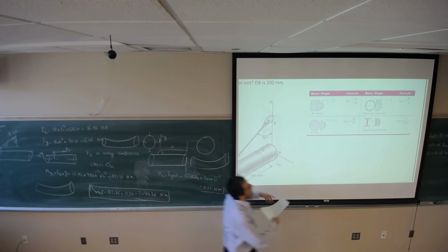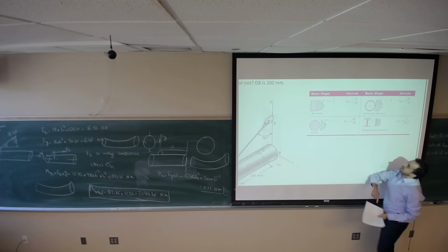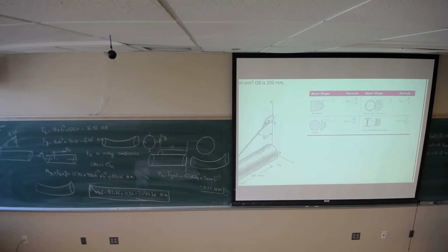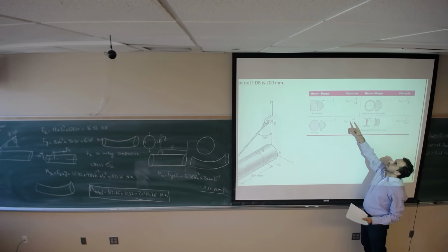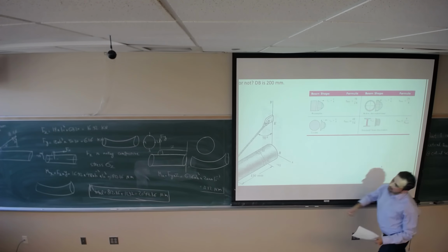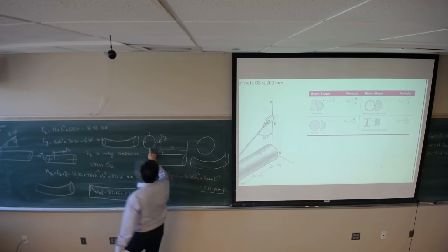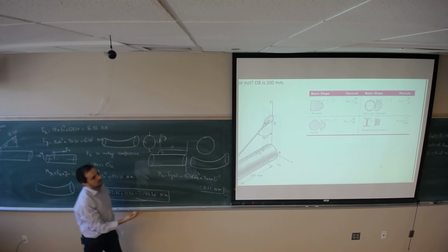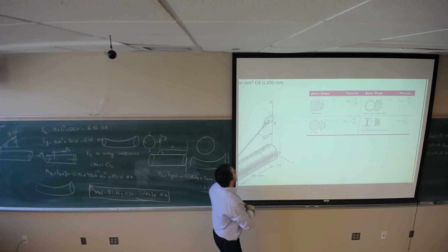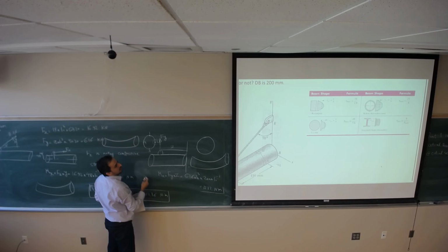The cross section that we have is gonna look like this. For transverse shear stress, the maximum occurs at the middle. At point 1 and point 3, the transverse shear is gonna be 0. Someone might say point 2 is gonna be the critical section.